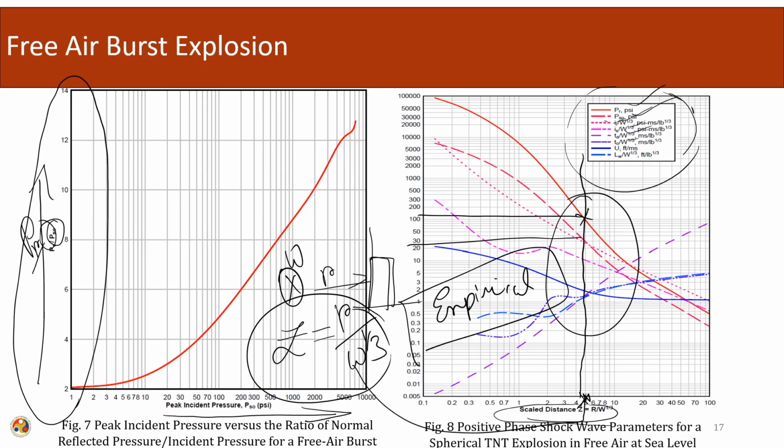If you are taking an envelope, we normally try to overestimate these quantities. This is a load parameter, so if it is overestimated on the upper side, then the loading value will be more, and the design of the structure will be over-conservative. So, though these values are easy to use, they are normally overestimated.